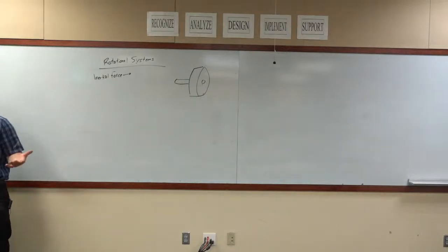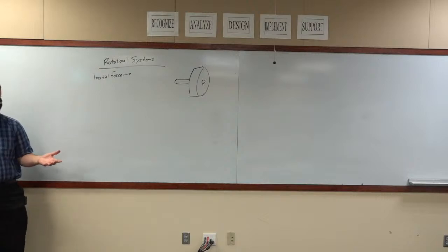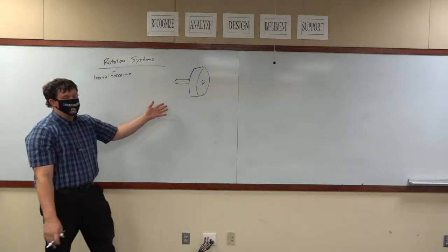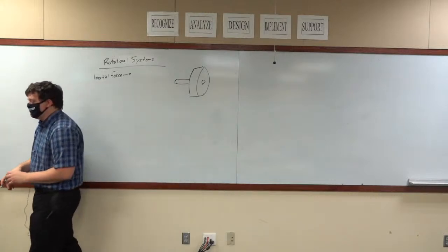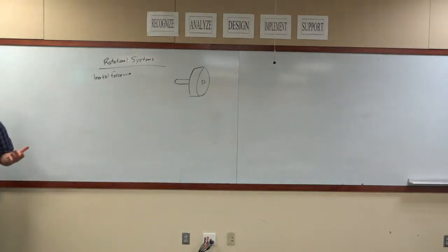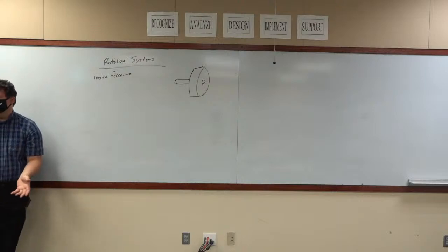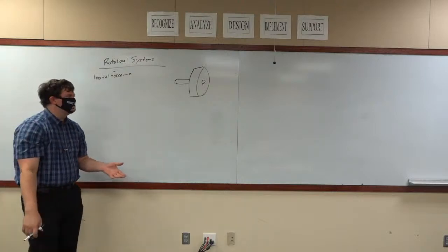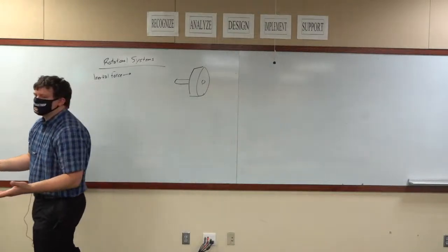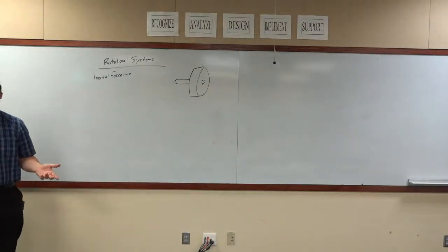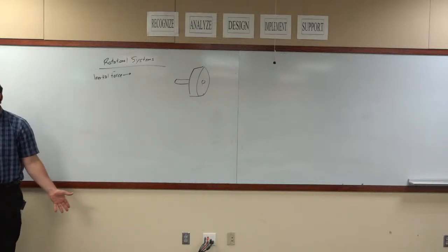For the same mass of wheel, the distribution of weight is going to change how hard it is to spin the system. It's no coincidence that a bike tire has all of its mass distributed around the rim, with very thin spokes. The reason is to maximize its rotational inertia, which actually gives the bike a lot more stability.